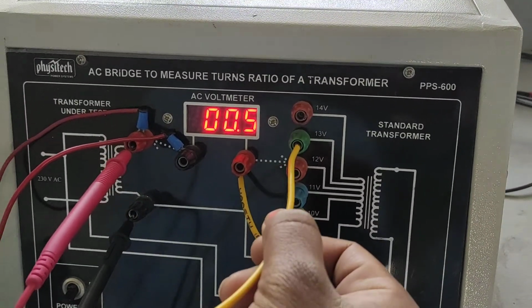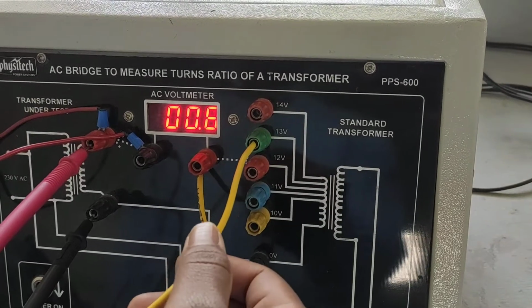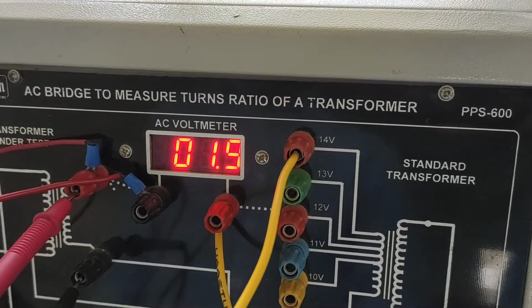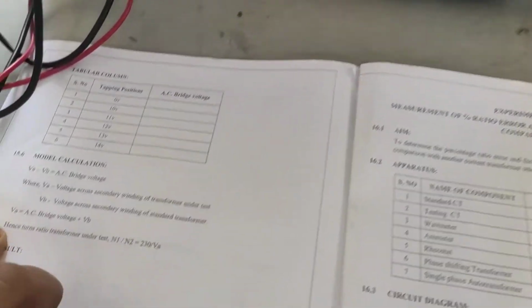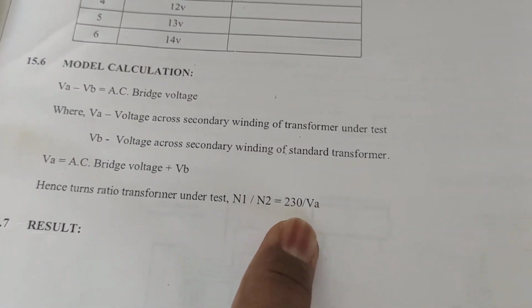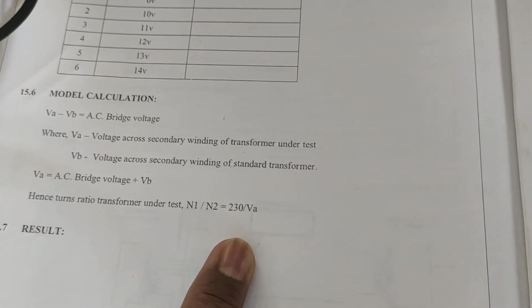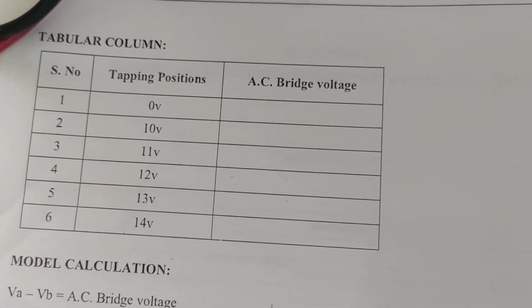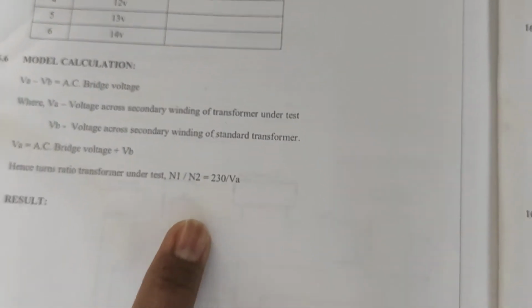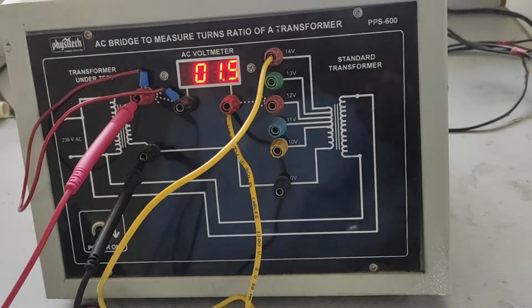Next is at 13 volts. If you see that 13 volts, again you will get the difference as 1, so it will show as 0.8. For 14 volts, it will be equal to 2. So these are the variations of these voltages with respect to the tappings. And if you want the turns ratio, N1 by N2, that is 230 fixed on the primary side, and the secondary side N2 will be varying depending on the voltage VA. So with those voltage variations, 10 volts, 11 volts, 12 volts, 13 volts and 14 volts, by taking that difference of voltages, you can find the turns ratio. Now if you take VA as a fixed 12, 230 by 12, then you will get the turns ratio. Now this is about the measurement of turns ratio by using AC bridge.